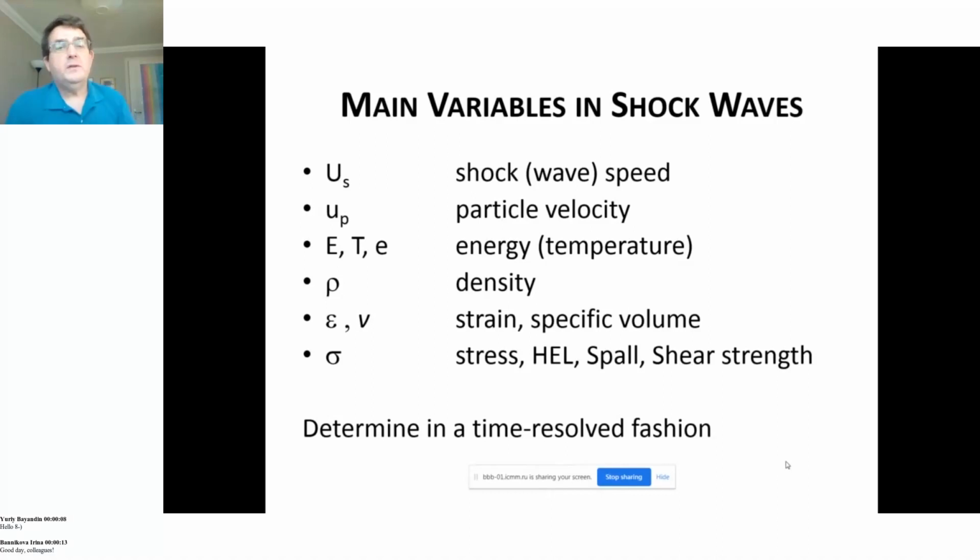When you're in those extreme conditions, there is generally a large stress wave called a shock wave, which is supersonic with respect to the material that it is launched into. Basically, so much energy and force is being delivered that inertia has a huge effect. The material does not have time to move sideways away from the oncoming stress.